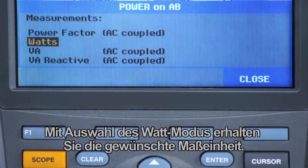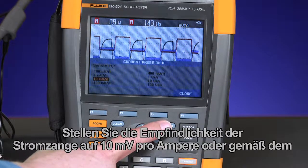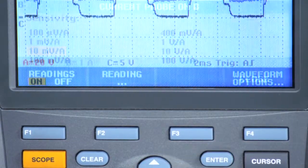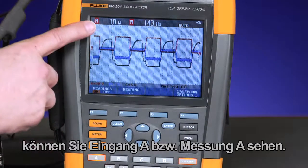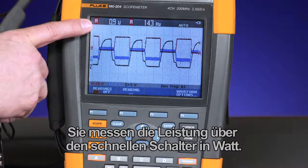Selecting Watts mode will give you the unit of measure you need. Scale the sensitivity on the input probe to 10 millivolts per amp, or whatever the current probe you have selected. Once you step through those key presses, you can see input A, or measurement A. You're measuring the power in watts across the fast switch.